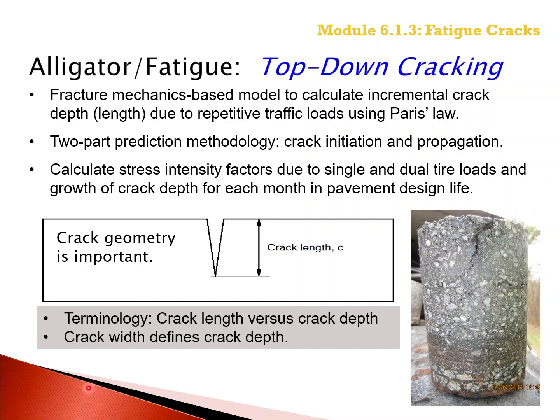Another important assumption used in the PMED design software is that the crack width at the surface was used to define crack depth from a calibration standpoint. The wider the crack, the deeper the crack growth. That assumption was used for calibration in the PMED software.